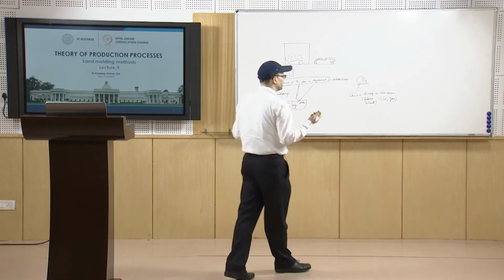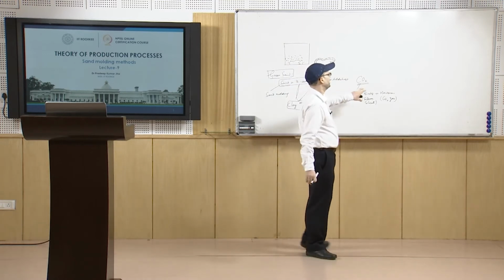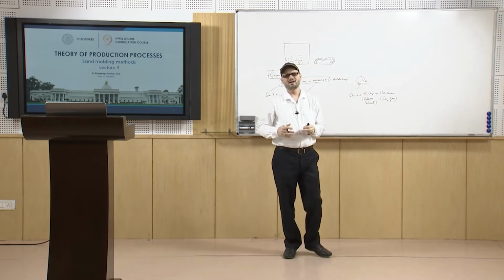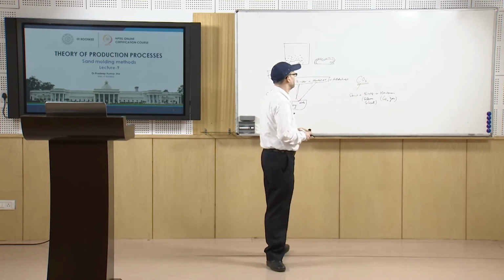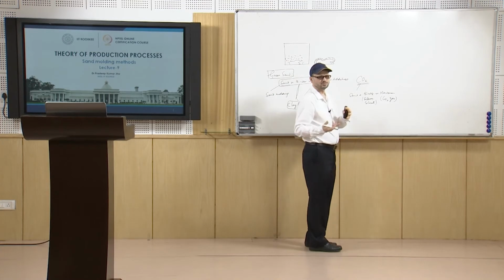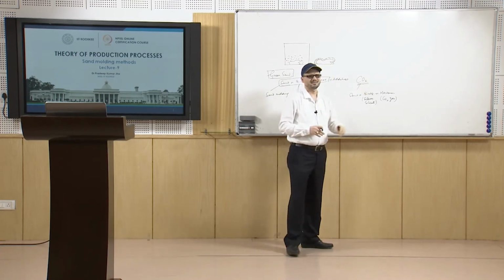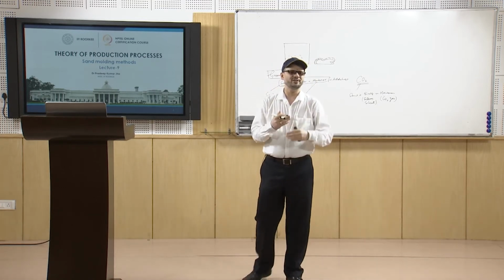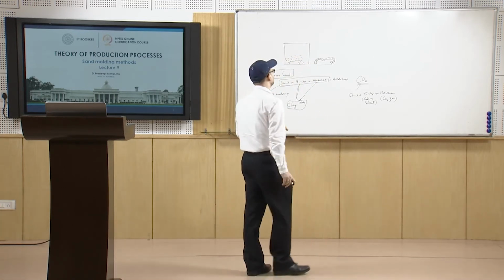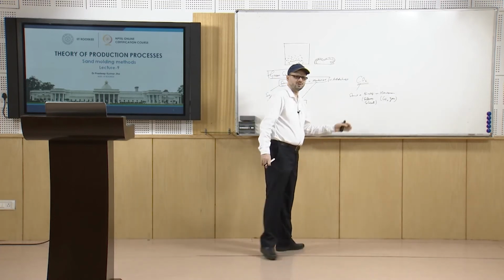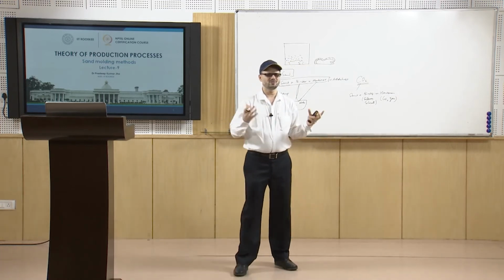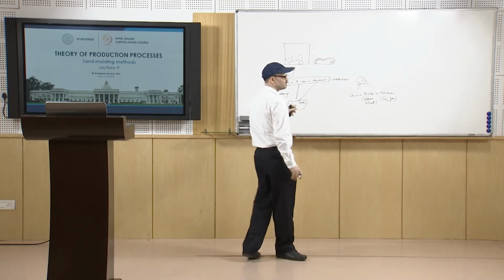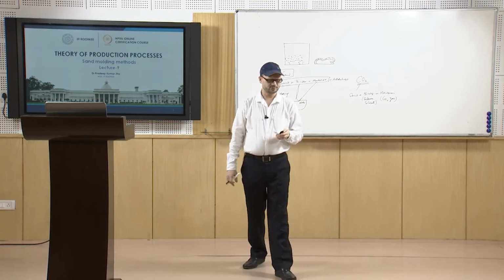So it has a certain bench life; you cannot leave it like that because it will harden, and then you have to remove it. One of the problems is that reusability is certainly limited in these CO2 processes, and work is still going on to make it reusable, because large lumps are formed which are not further reusable. So, that is the CO2 molding process.